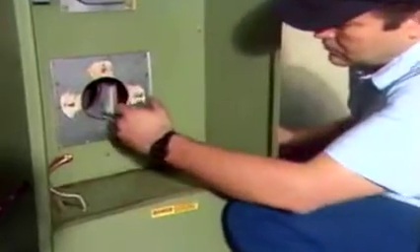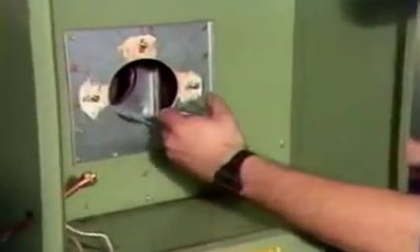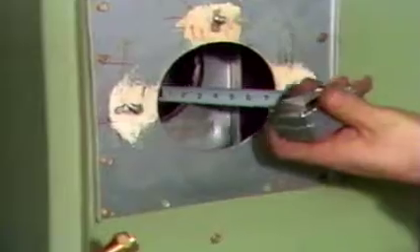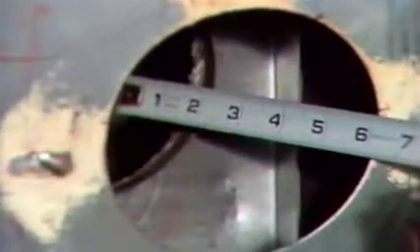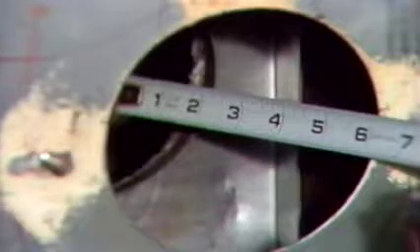When insulating material is not available and the chamber opening is larger than 4 3/8 inches, the burner end cone setback should be increased slightly, but care must be taken to avoid oil spray impingement on the entry walls.